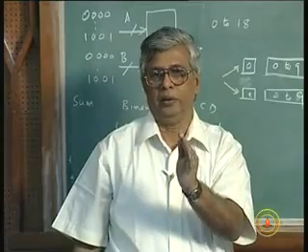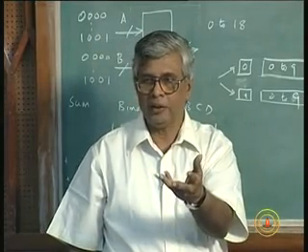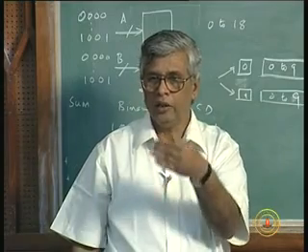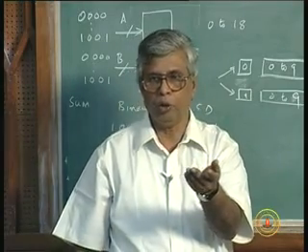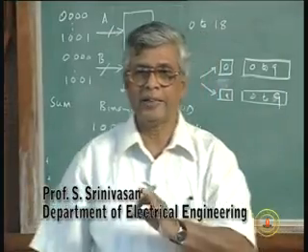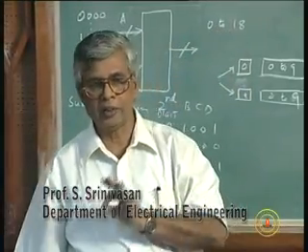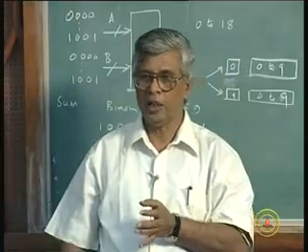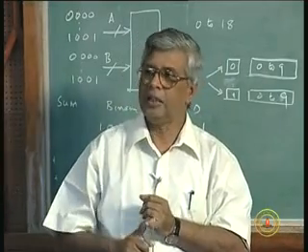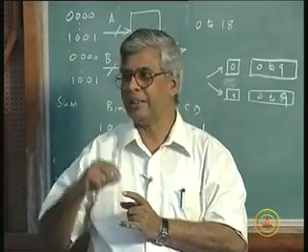6 has to be added, no problem. I have to take another binary adder, a 4-bit adder, and add 6. But it is not that simple. I can only add 6 under certain circumstances. What are the circumstances under which I have to add this 6? It depends on whether there is a carry in the original addition, or whenever the number exceeds 10.